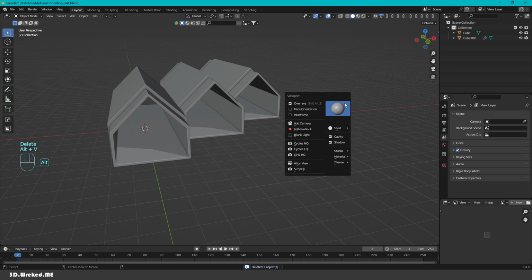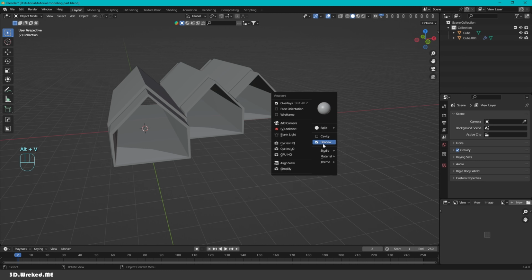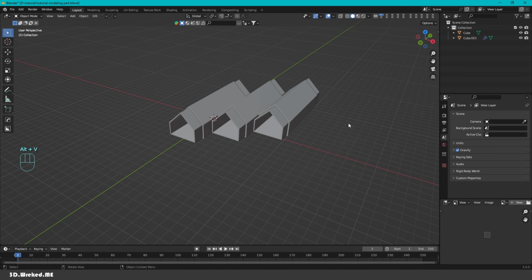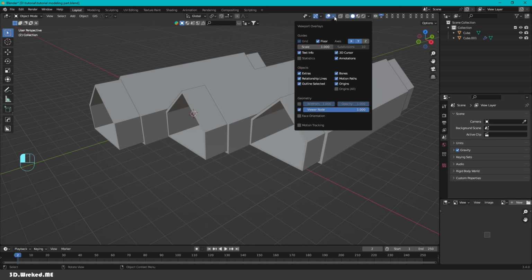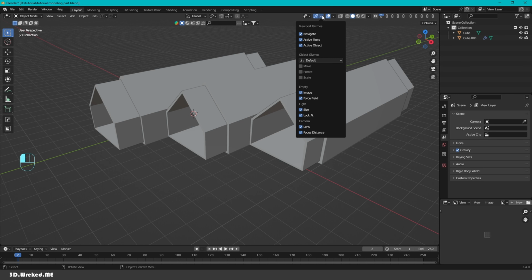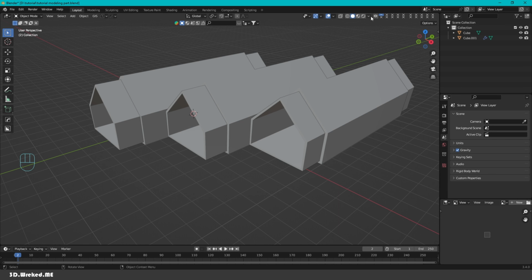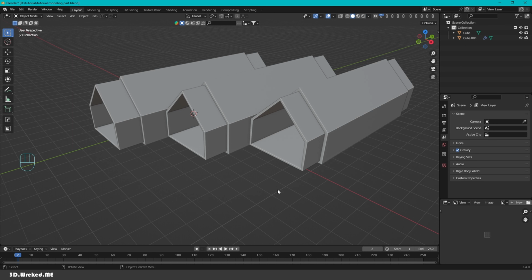Let me press Alt V to take out the cavity, and another Alt V to take out the shadow. It's probably what you have now. You can activate the same things from the tab above. Where was it? I can't even remember. Cavity, you can add ridge cavity and so on over here.